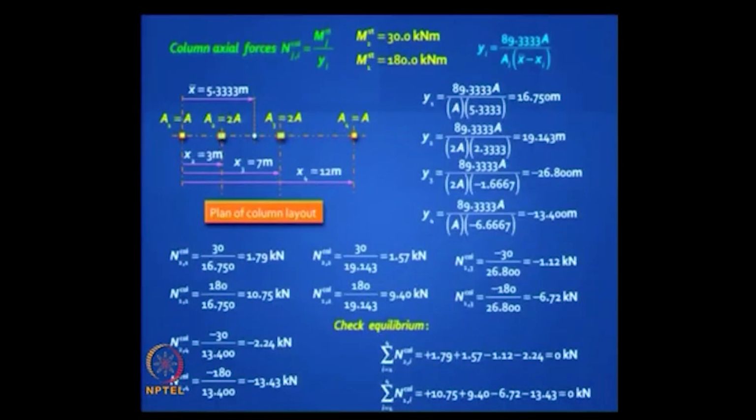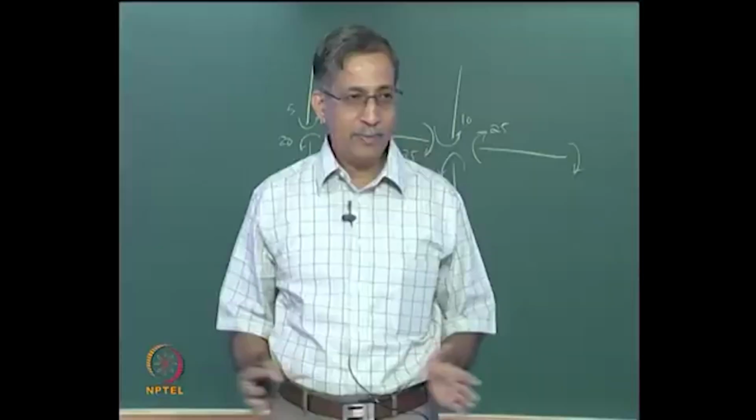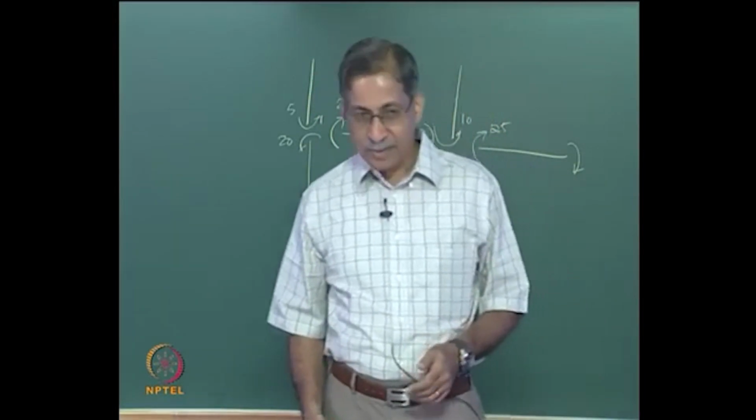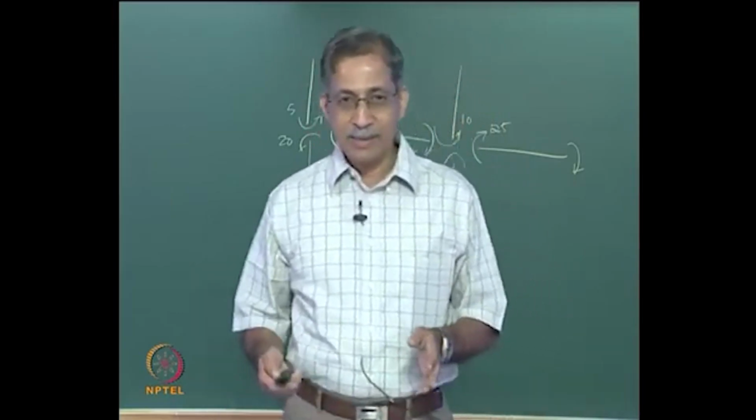So can you all do this step? Of course I will give you the choice, you can do either portal or cantilever. For the assignment you have to do the cantilever also, but in an exam it is too much to do. So you just do the assignment. In practice both are approximate. People say that the portal method is more accurate when you have a wider frame, not very tall, and the cantilever is more accurate when you have a very tall frame with narrow width, but it all depends on the relative areas. Okay, so here I will go quickly, we are doing the same thing.